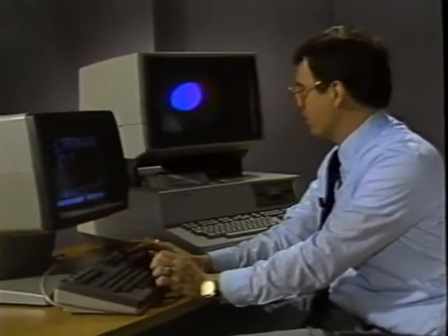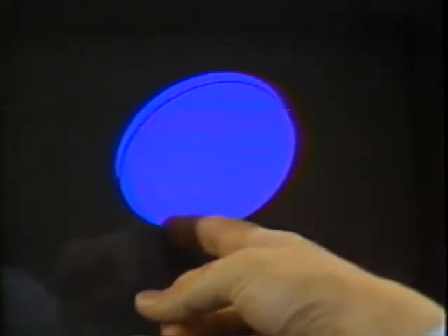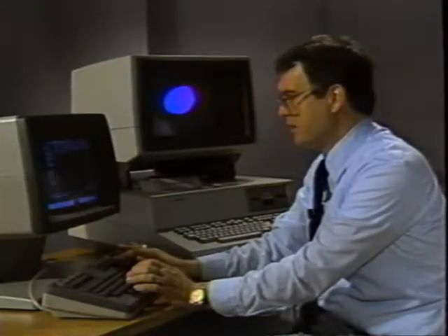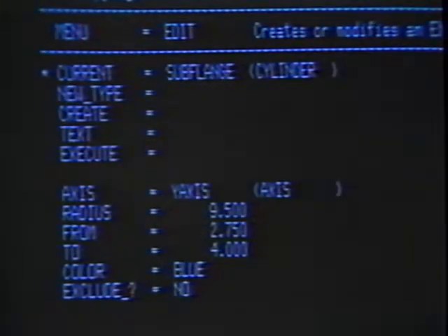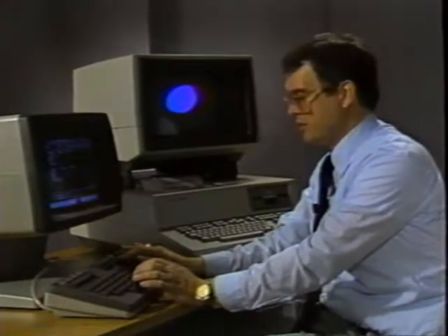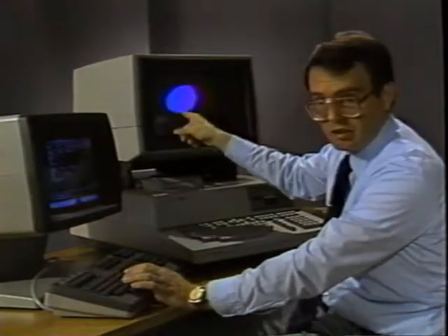We're now ready to continue our design. We have called up the cylinder with the color dark blue, and we want to add the bolt holes that you saw in the graphic display a minute ago. So back into menu Edit. We now call up the element cylinder, assign the radius, the from, and the 2 point, and the color yellow, and then we rotate that cylinder to give us the primitive that will become the bolt holes that will be subtracted from this disc here.